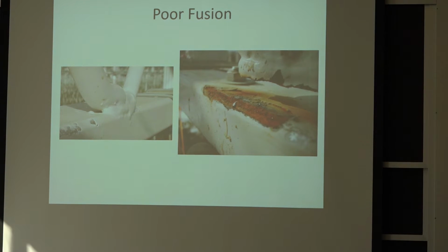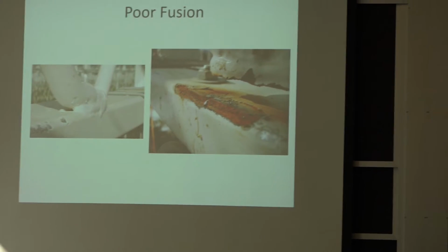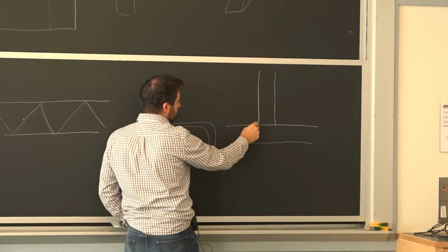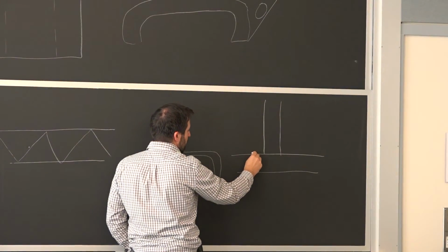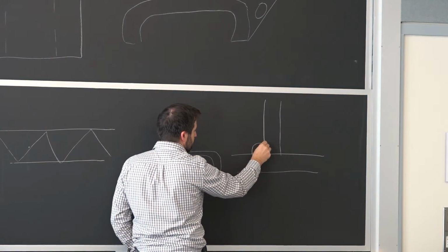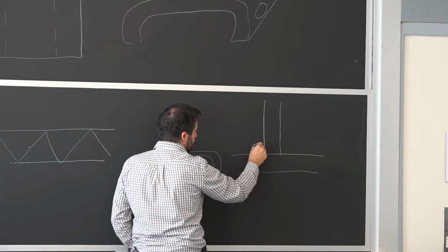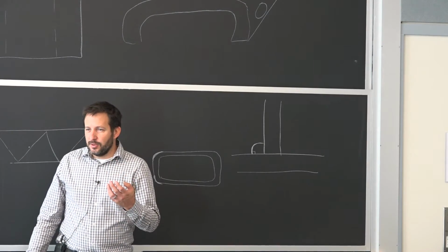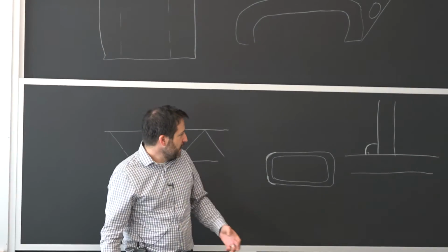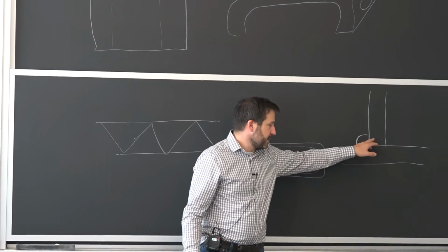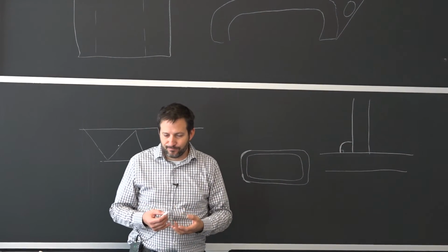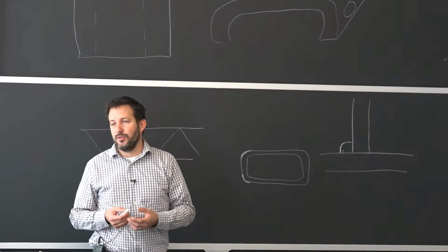So when we talk about poor fusion, and we'll do it on a straight piece this time, so it's a little bit easier. So let's say I'm making a T connection. It's very, very common. And I'm going to come and weld. When my weld bead looks like this, just comes in at 90 degrees here, it's a little bit intuitive to think that you didn't heat up that material that much, in this case this material as well, because your surface tension was very high there.